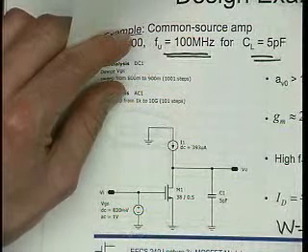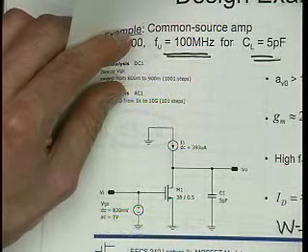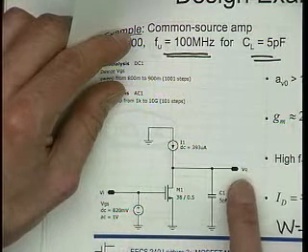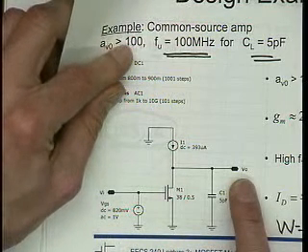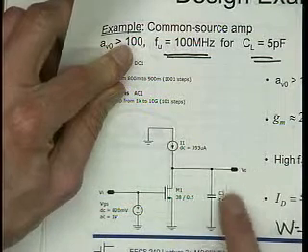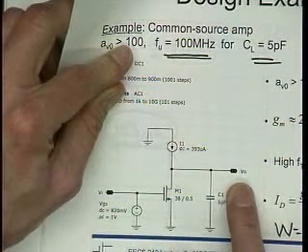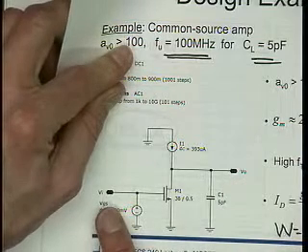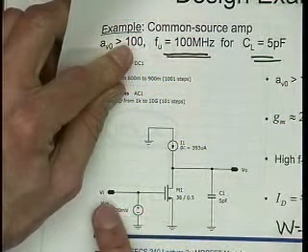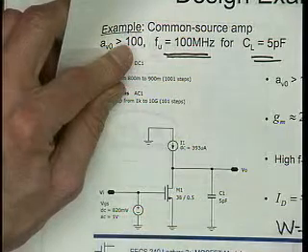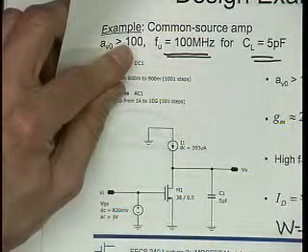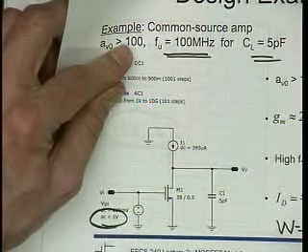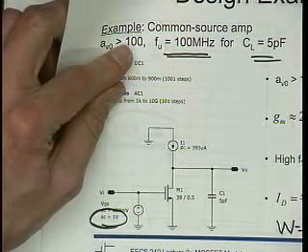And then 1 volt has one very trivial but very convenient advantage. When I want to plot the gain of the circuit, normally all I plot is Vout. In reality, I would have to plot Vout divided by Vi, which of course I could do, but if Vi is equal to 1 volt, I don't need to do that division. So it is pure laziness why in just about all my AC analysis, I use 1 volt.